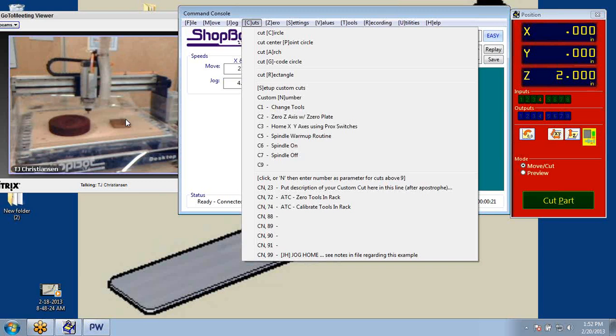So what I do is I come in here and I run my spindle warm-up routine. You're just pretty much letting your spindle run for about 6-7 minutes, and it's throwing lube around on all the bearings and re-oiling them up before you put pressure on. So always run a C5 first. Always run a C5 the first cut you do of the day. Before you even cut, just turn that on and run it. So do your C5 and then go and do your C3 and your C2. I forgot to touch on that one.